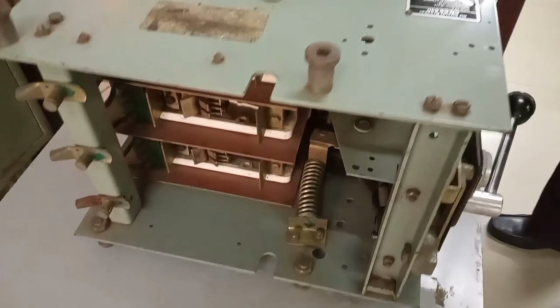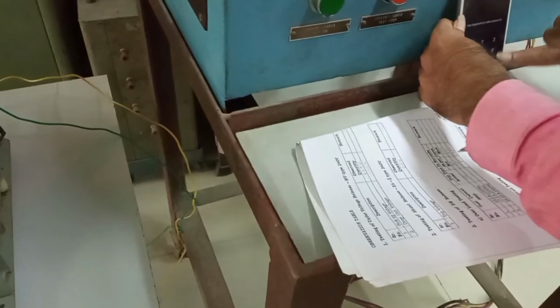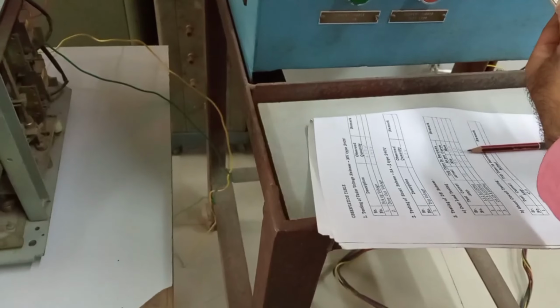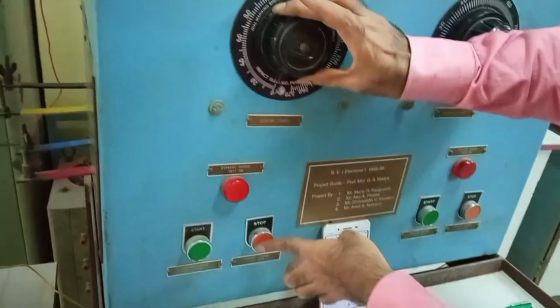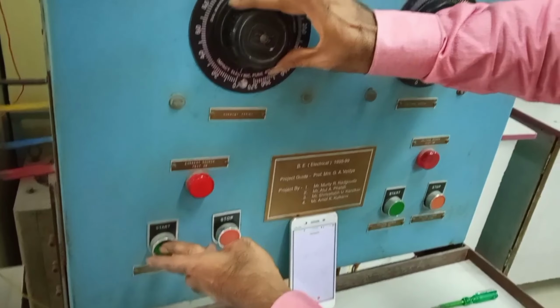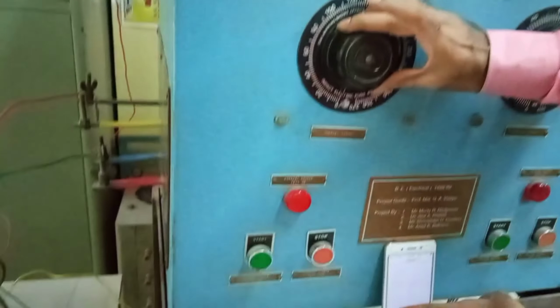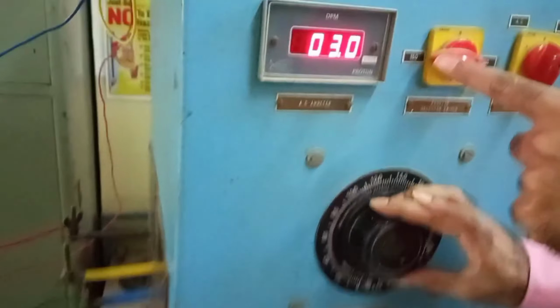Now the breaker is in a closed position, and now I have to inject current. How much? 17.5 ampere through this, for overload testing. Okay, and at the same time I will switch on the timer also. So see, I am injecting the current. I have injected the current and I have started the timer also. And see, now the timer is started and I am injecting the current.